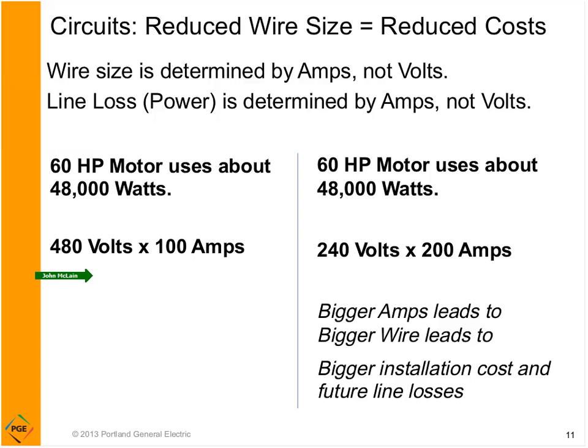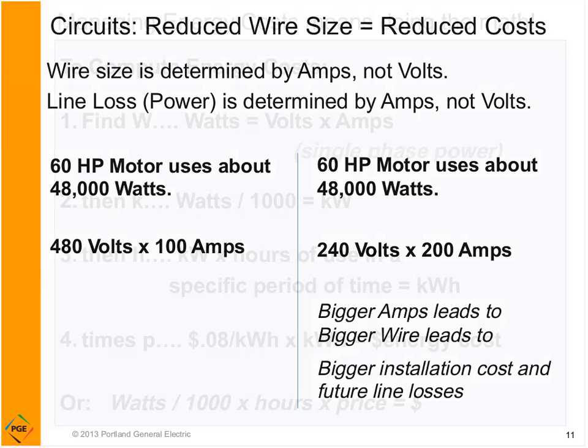And if this equipment says, oh, I have to go past 1,000, you'd have to replace the whole panel to get larger capacity. Changing the voltage of the equipment can reduce the amps. So this is a nice little chart to remind you of that. Watch out for purchasing. Check not only the watts and the efficiency, but the voltage can often be another way to reduce your energy costs at installation.